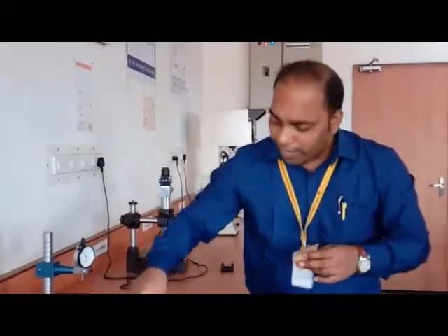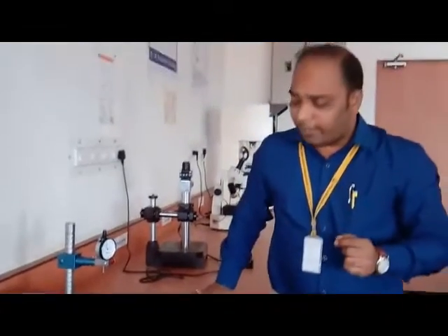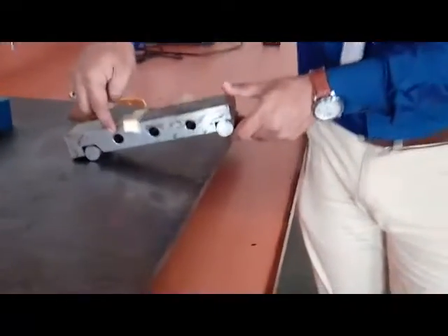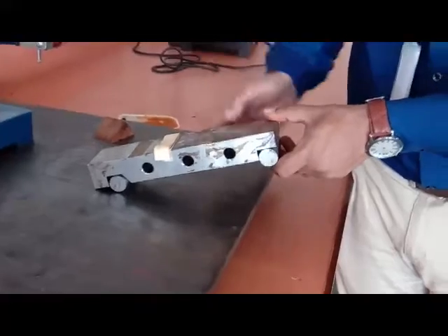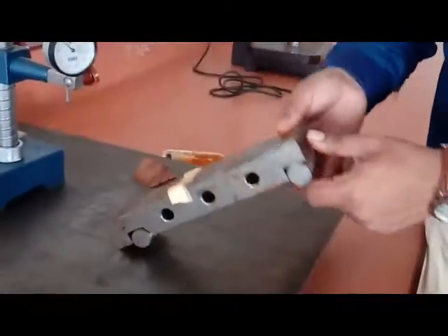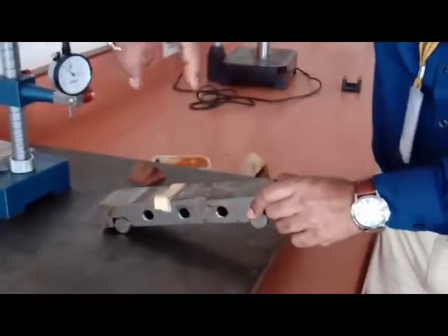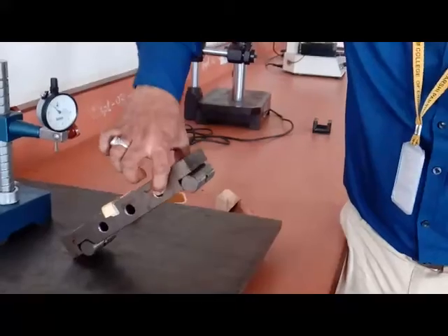The workpiece itself acts as a surface plate, but an external attachment is used, and for that external attachment, this sine bar has different holes in it. These different holes serve two functions. The very first function is for reducing the weight of the sine bar so that it is easy to use, and second is for any auxiliary attachment. It can serve as a tangible limit over here.